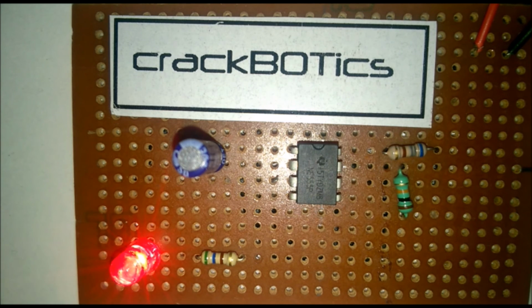Now the question arises: where will we find its application? The frequency that I am getting over here is 3 Hz so that it can be clearly visible. This can be used to give any message, any signal or anything. This IC 555 can be modified, and different sets of values of resistors and capacitors will give you different frequencies. For example, it can be used as an inverter also, where you will just need a transformer and 2 or 3 MOSFETs according to your ease. So this is how we can find its application.